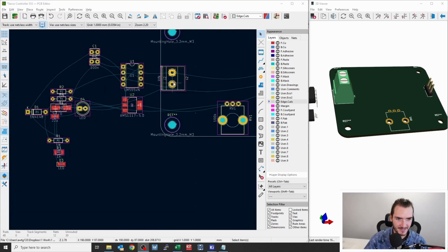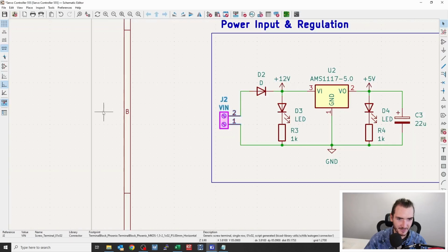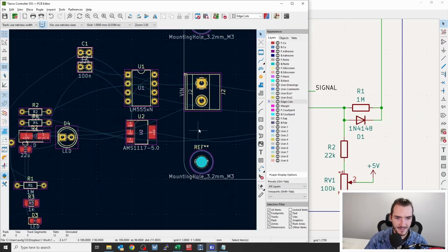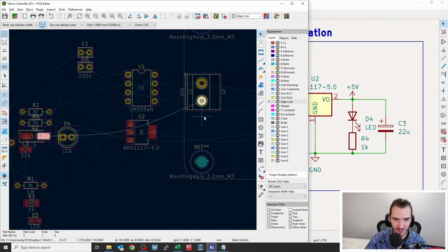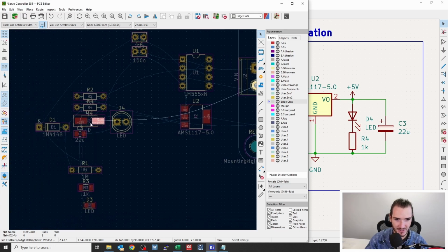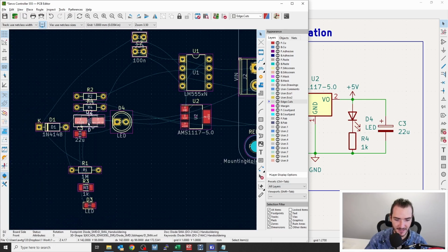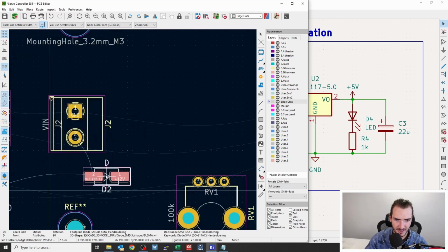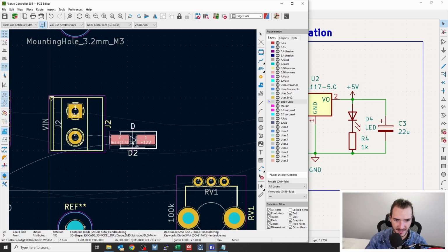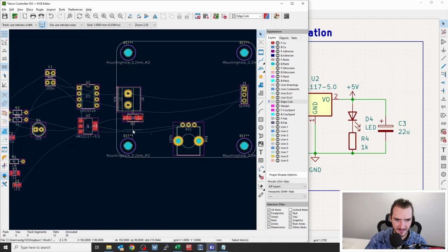I know that next we are going to connect through the diode. So we go from the screw terminal into the diode and then into the regulator. Now I can see exactly what this connects to with that curved ratsnest line, but I can also strike the caret key, which is to the left of the 1 key, and that shows me that the next thing that I want to connect to is this diode. So I can grab that diode, strike M to move, and I'll just place that right near my terminal. Maybe down the bottom there makes sense.